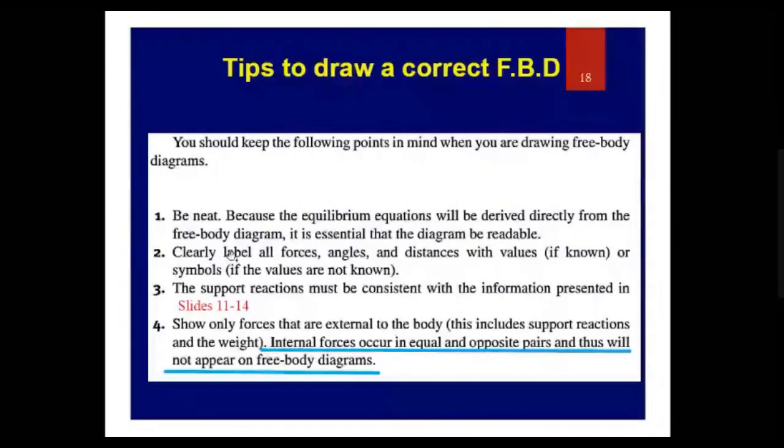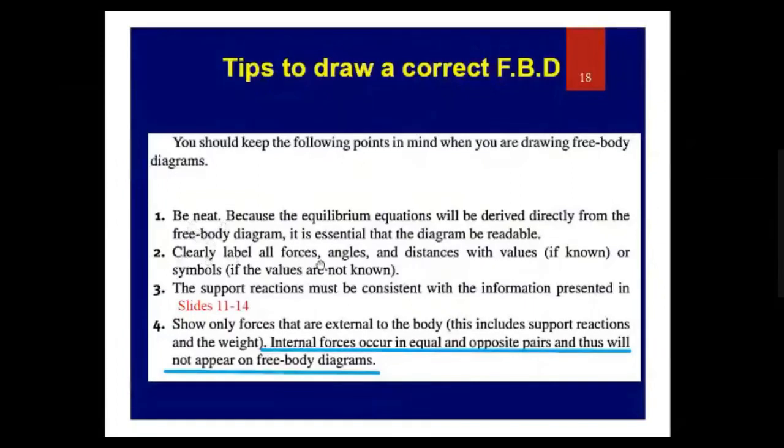After drawing a correct and neat figure, label all the forces, all the angles and distances with values if known, or with symbols if they are unknowns. The support reactions must be consistent with the information presented in the previous slides. So you should know what type of reaction forces will develop if I remove a particular support, whether it's a roller support, a hinge support, a cable, or a link.